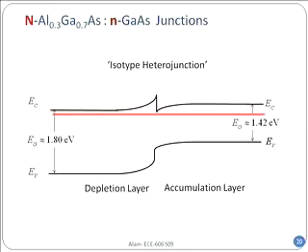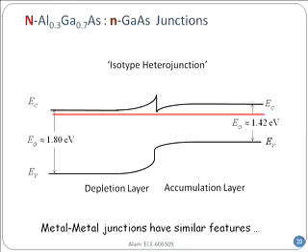Here, however, on one side, yes, charges have been pushed back. And so, on the larger band gap side, yes, you can have this depletion charge. But look at the other side. In fact, charges have come in because it has gotten closer to the Fermi level. So, therefore, I cannot use my standard depletion approximation, Q, V_bi and all those formulas. Now, how do you calculate it? Well, that will be another course where you will learn how to do this. But for the time being, you can just understand it, and if you do numerical simulation through nanoHUB, they will do all these things automatically. So, you don't have to worry about it.